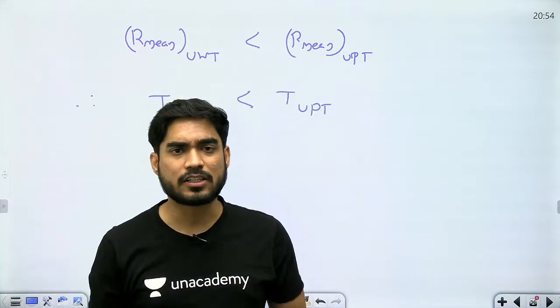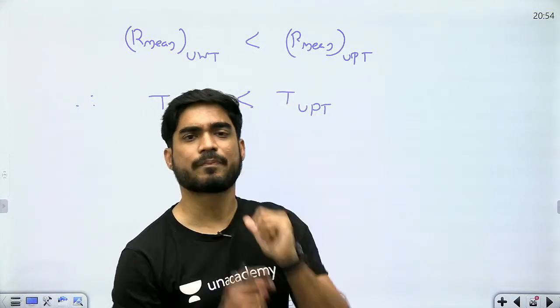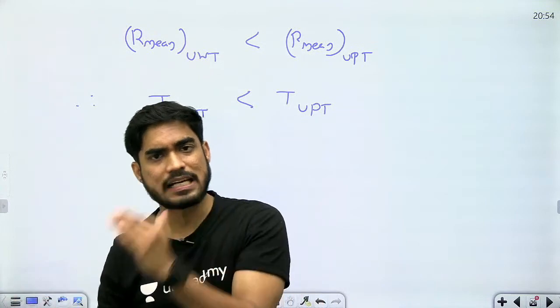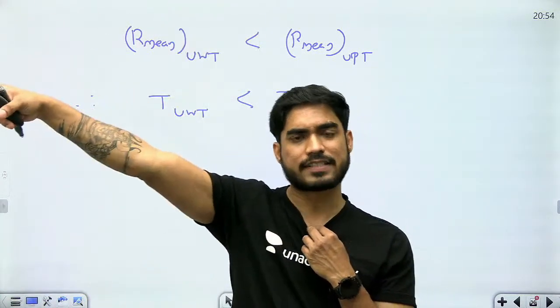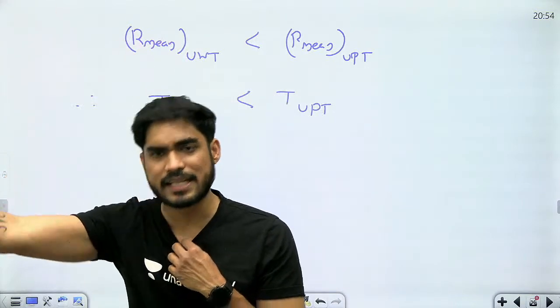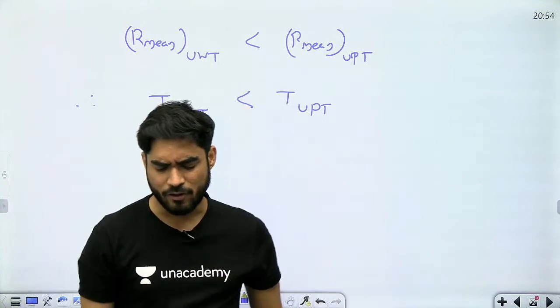You will not assume the torque transfer you are getting initially, because that is only for a very short period of time. Afterwards, you will get less torque transfer. So if your torque is going to reduce after some time, you will assume that is your maximum torque transfer. And I have told you this concept before also.